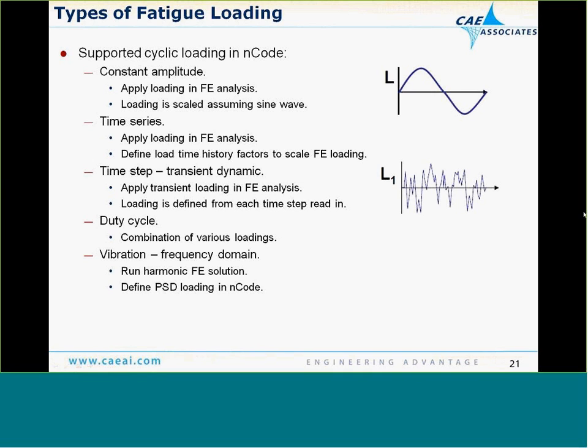It could be a complex time series or test data that you're going to apply as your cyclic load. So you maybe would apply a unit load in ANSYS, and then you would tell it how that load actually cycles by using the time series. If you have a transient dynamic analysis and you really want to use every single step of that transient analysis to define your cyclic loading, you can do that with the time step approach.